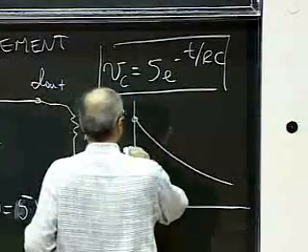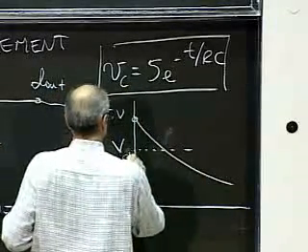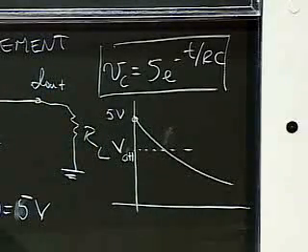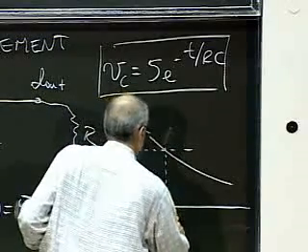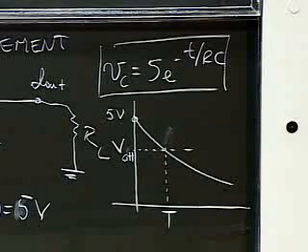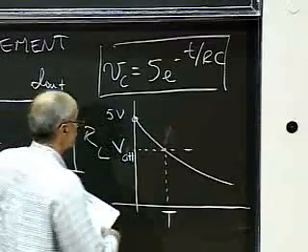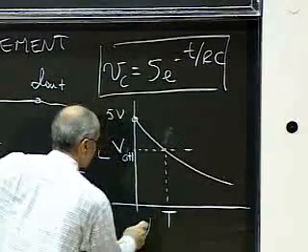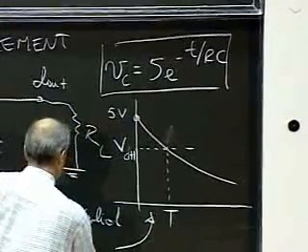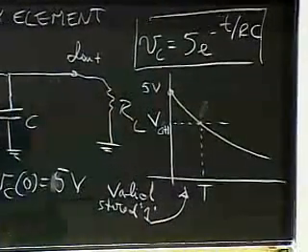going down towards 0. At some point, we're going to cross the threshold for high, okay? So the only period in which I have a valid output, if the capacitor was storing a 1, is this period here, okay? So this is the only period in which I have valid stored 1.